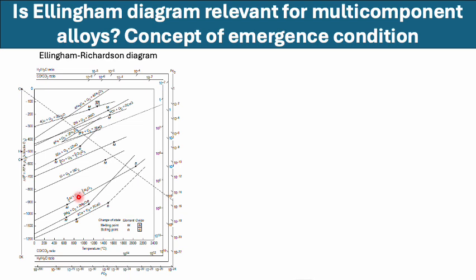Pure aluminum should not even be there in solid state beyond 660 degrees Celsius. But aluminum in a nickel-based superalloy can still stand until the melting point of the alloy itself. So the oxidation of aluminum present in the alloy will definitely be different from pure aluminum oxidizing.